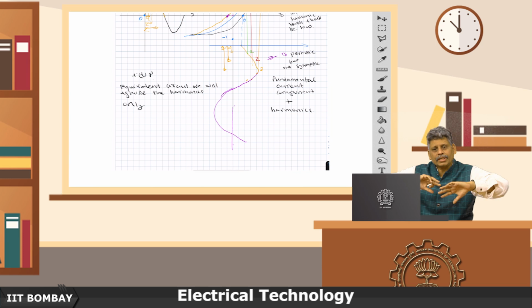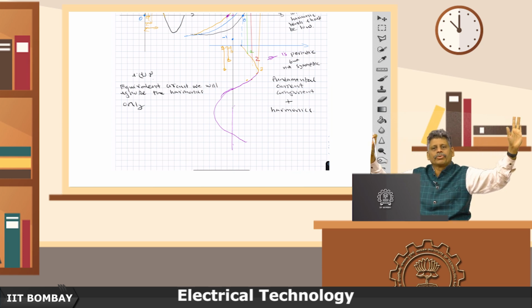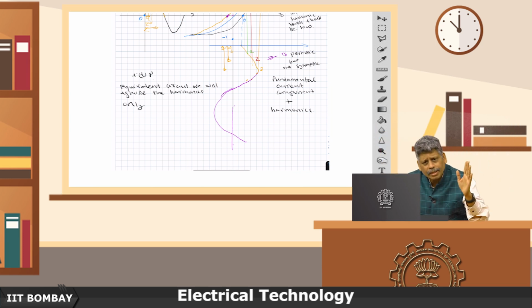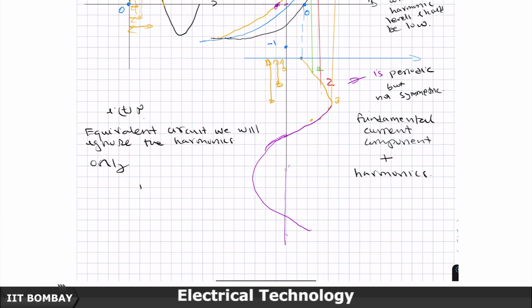So for example, on a digital storage oscilloscope, you can record the current waveform, then you can calculate the first harmonic and then look at V1 by I1, the first harmonic or fundamental component, and see this magnetizing component part. This ratio should be equal to jXm.